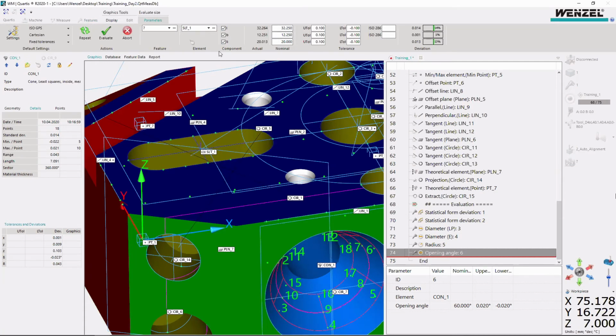1. And then first is the L, which is the length from one extreme end to the other extreme end, and the nominal value is 32.25, and then we will get this value. And then upper tolerance, lower tolerance, the rest is the same. And then B will be the width, and then Li will be the center of this circle, this one. It will be a point, center point, to the center point of the other circle, and it will be 20.